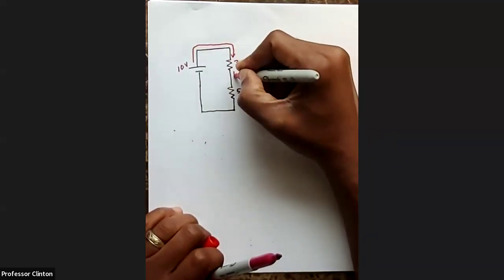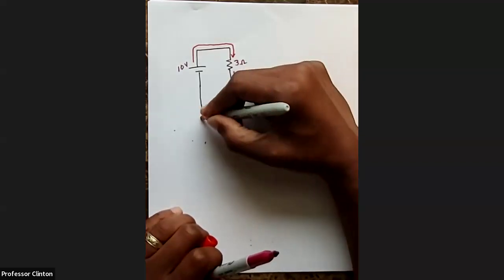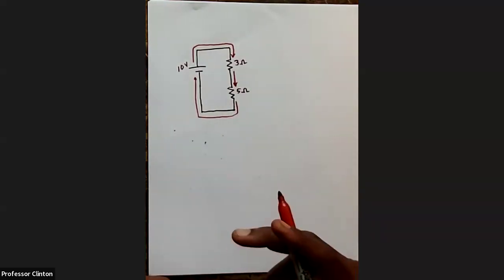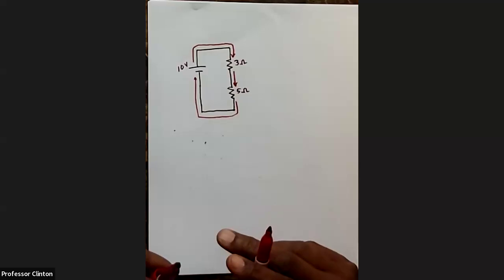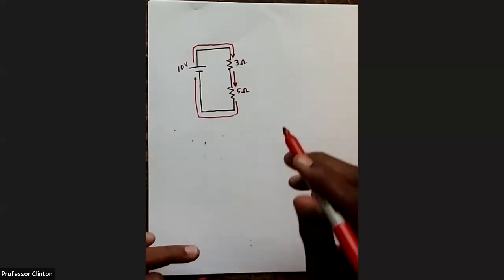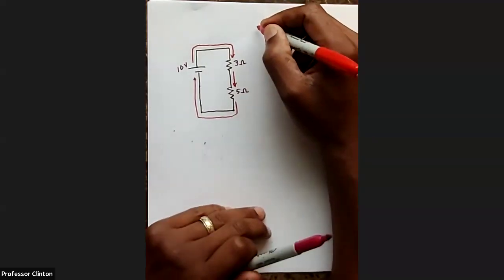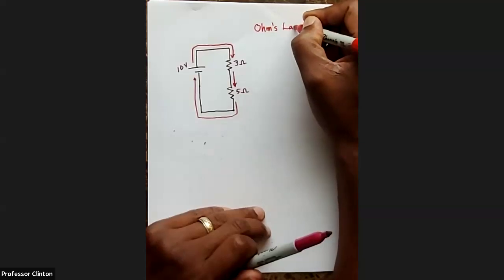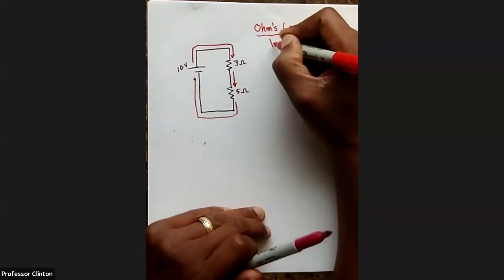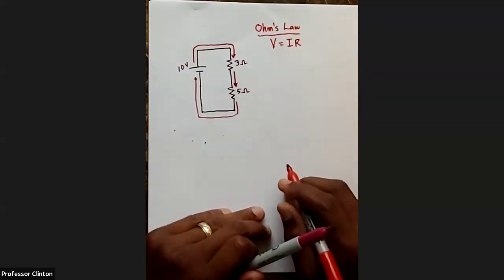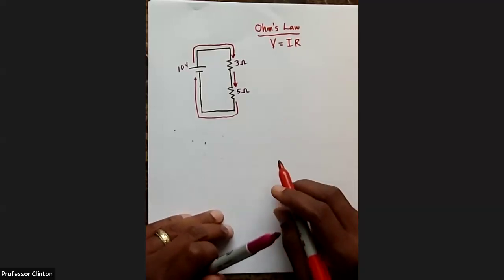So our current is going to flow through here, around, and back. And there's also something called a voltage drop. When we talk about the voltage divider in just a second, you'll see how that all plays out. So 2 things to note. The first thing to note, we've come across this already, is Ohm's law. Ohm's law says that the product of the current times the resistance is equal to the voltage. So that'll be one component that we look at.